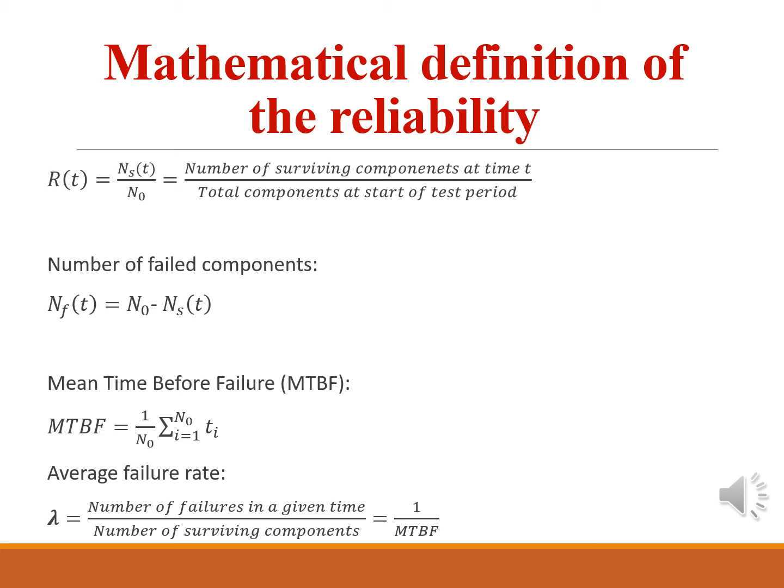The semiconductors and integrated circuits that are required to have high reliability are subjected to burn-in periods from 100 to 1000 hours, often at high temperature and excess voltage, to induce failures in any suspect devices and to get beyond the initial low reliability part of the bathtub curve.